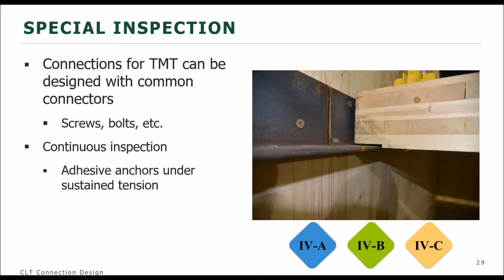So other than when you've got adhesive anchors resisting sustained tension loads, you would only need periodic special inspections of your connections. And the reasoning for this is most of the connections associated with these new mass timber elements are very similar to the ones that we've used in traditional heavy timber.